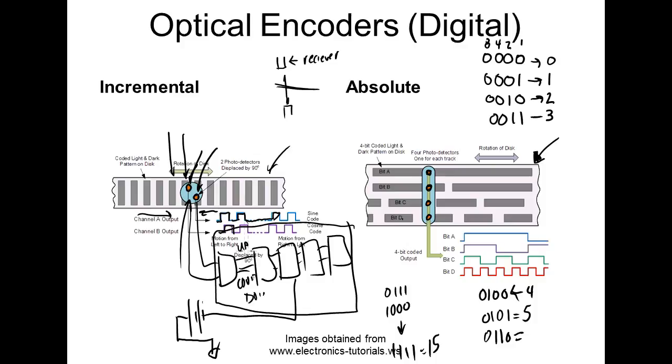Well, you can recover. We call it mastering the robot. If the robot ever loses its position, we'll go over and look at some of these robots. Then what we can do is what they call a rough calibration by lining up marks. We jog the robot and line up marks, and then we tell the controller to use that as the origin. That's referred to as a rough calibration. It probably works. You're going to be able to get that thing within less than a millimeter, which is usually okay for any application.